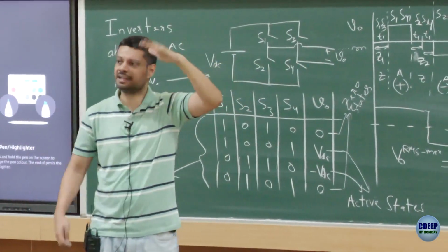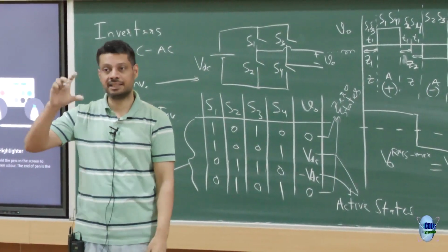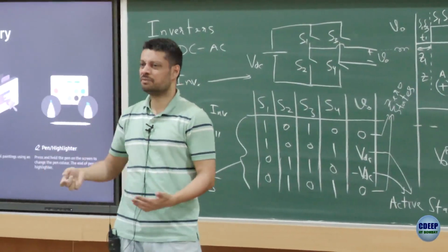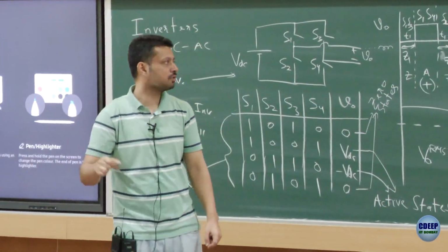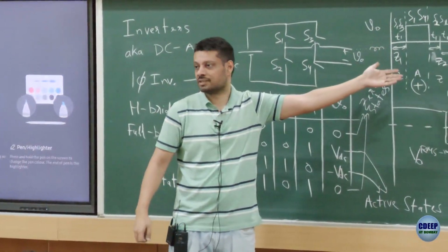You connect it to the fan, it works, it rotates, of course. There's a sound, and it's not only the sound, internally there is a torque oscillation also happening in that. You are losing efficiency, your torque is jerky, so you don't like it. So the objective is to minimize as many harmonics as possible.